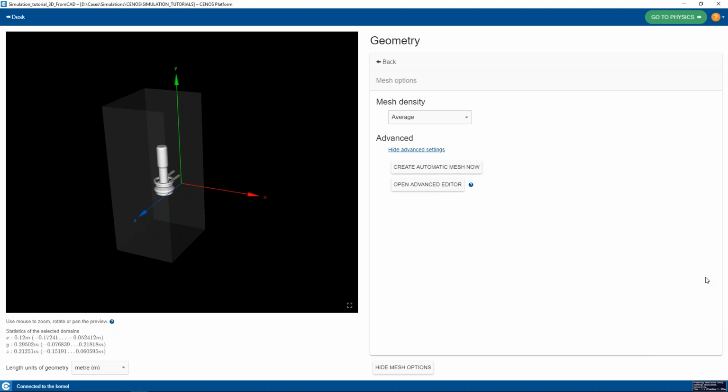If the mesh is too coarse, it will run very quickly, but the results can be incorrect. So you still need to keep some level of resolution for the geometry you are working with. That is also an aspect of an optimal mesh, which makes some kind of limit to which you can refine your geometry.